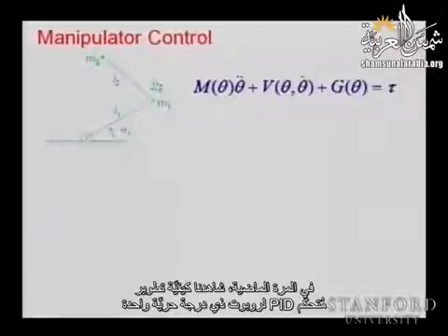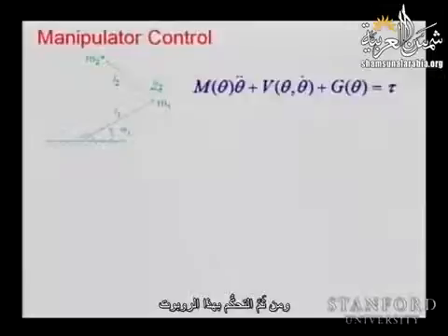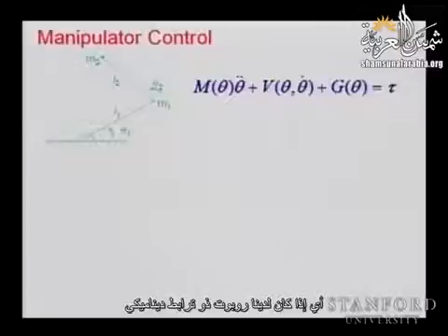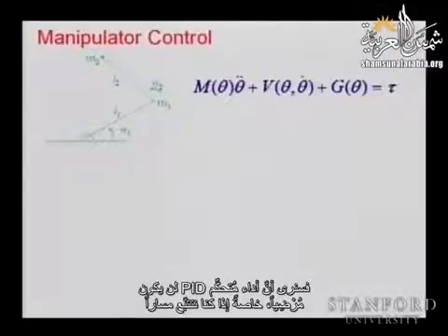Last time we saw how we can develop a PID controller for a 1 degree of freedom robot and then deal with the control of that robot. If we add 1 more degree of freedom, that is, if we have a robot with some dynamic coupling, we are going to see that the performance of a PID controller is not going to be satisfactory, especially if we are tracking a trajectory.